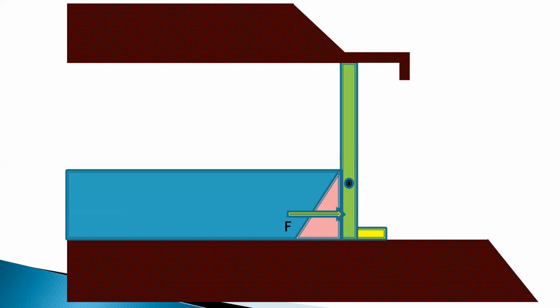Okay. So you can see here. This force point is also moving in the upward direction and it is gradually approaching this pivot point. Once this force crosses this pivot point, suppose the force is acting at this point, okay, then it will create the moment in this direction and it will slowly try to rotate this gate.